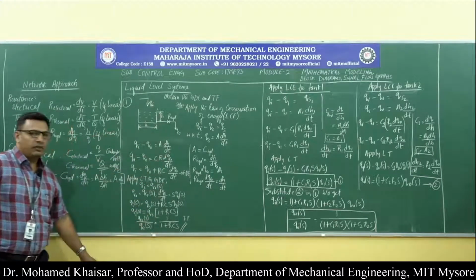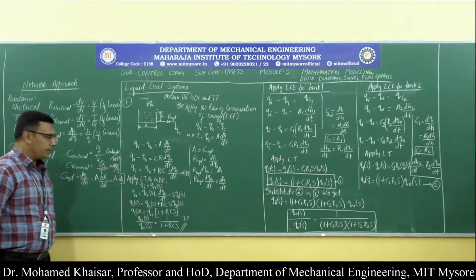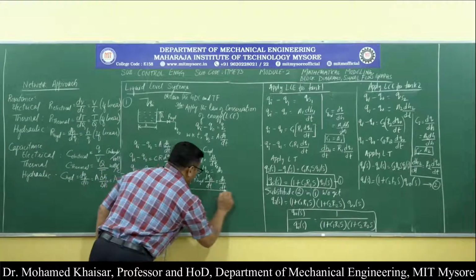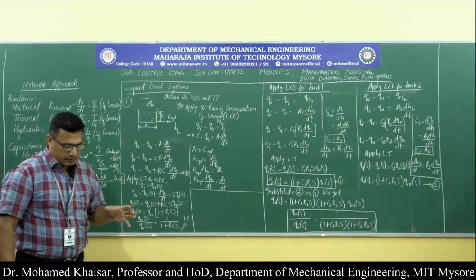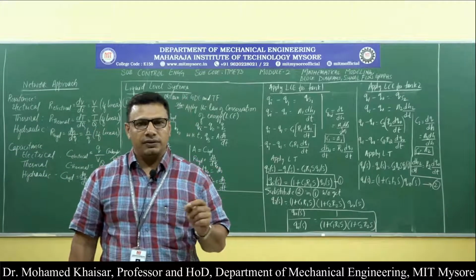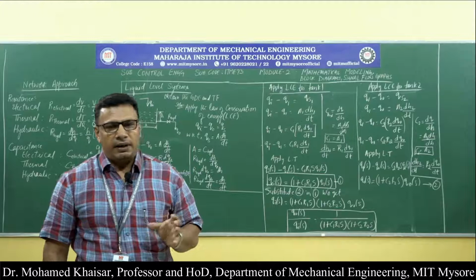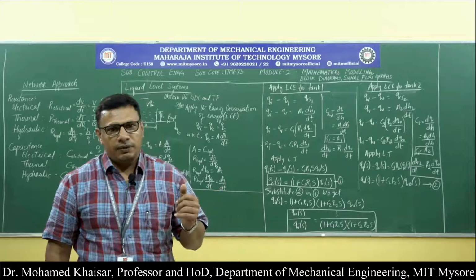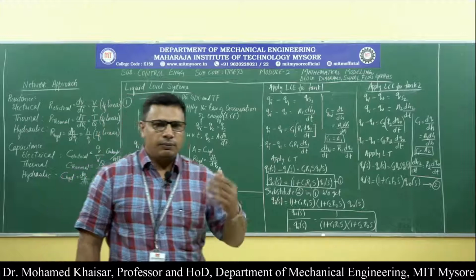This is the simplest way in which we can arrive at the transfer function for such a problem. Now, let me take up, just like in mechanical systems, where we started with the simplest single mass spring damper system. Even in liquid level systems, we can have more than one tank, just like we had more than one mass. We can have two tanks, we can have even more than that.